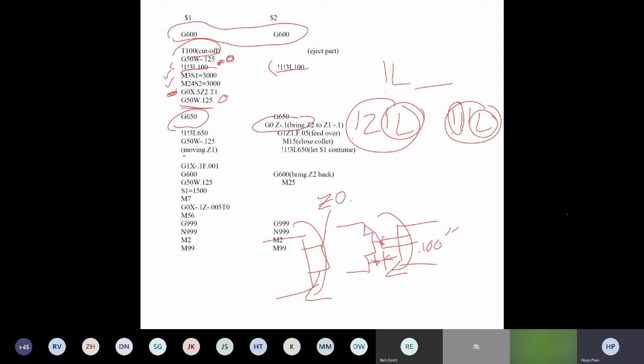Instead of calculating the whole distance in order to know how much you have to move forward with the sub spindle, and then how much you want to move again in order to come in and pick up the part, it makes everything way simpler by telling the machine that the sub spindle is gonna be Z0 for the dollar sign 2, and the face of the part is gonna be Z0 on the main spindle.